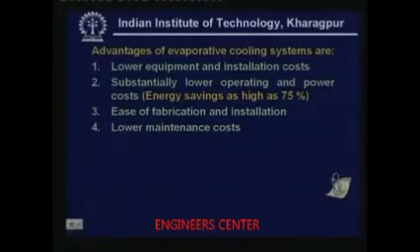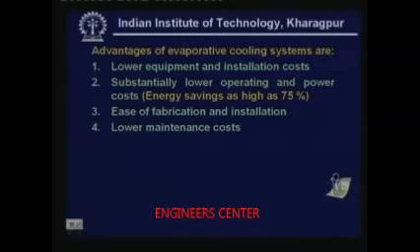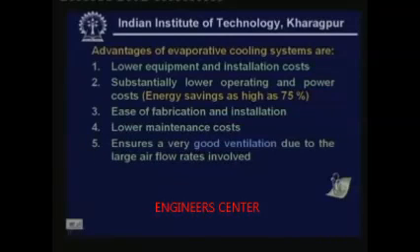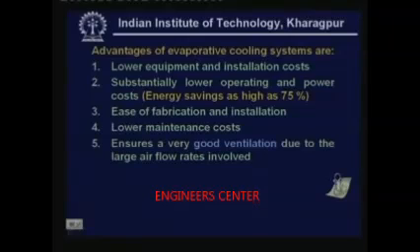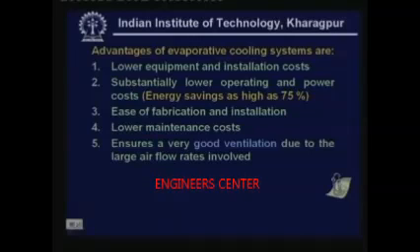And the lower maintenance cost: since you do not have any compressor, the maintenance cost is considerably reduced. So, this is another advantage, and these systems ensure very good ventilation. This is because, as I have already mentioned, the required air flow rates are very large in these systems, and typically in these systems you do not recirculate the air. Whereas in a conventional system you recirculate the air, in an evaporative system you exhaust the air. So, you continuously draw fresh air, cool and humidify it and supply it to the conditioned space. So, not much recirculation is used. Recirculation is not very effective also.